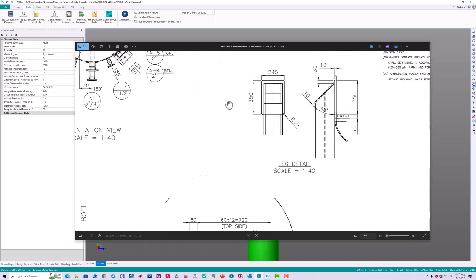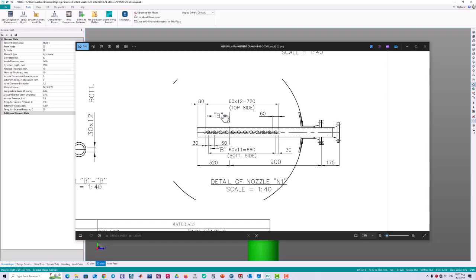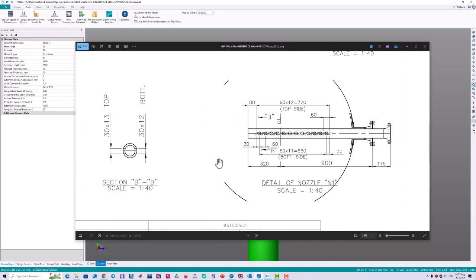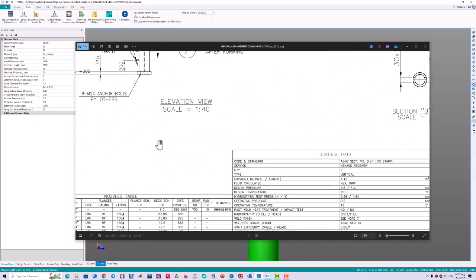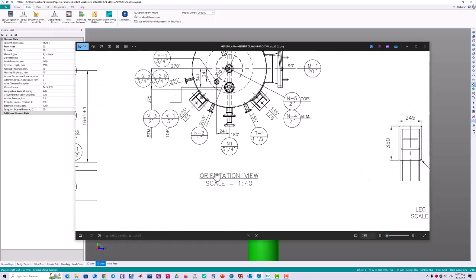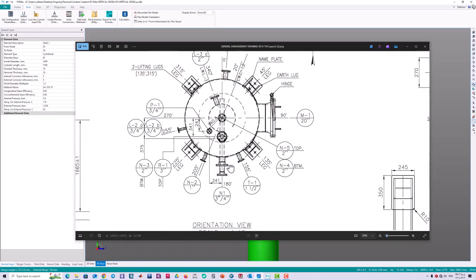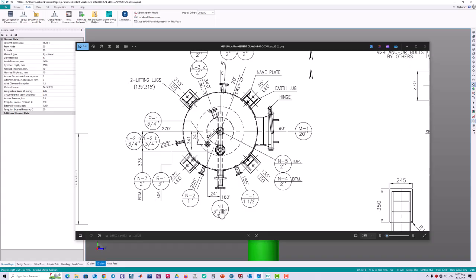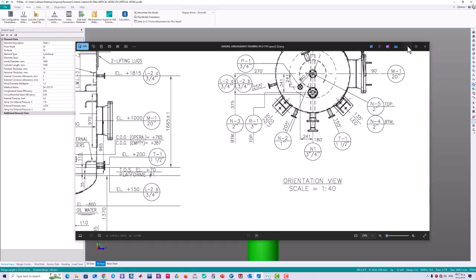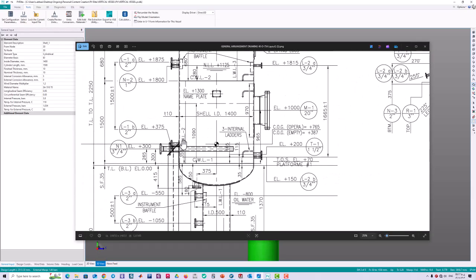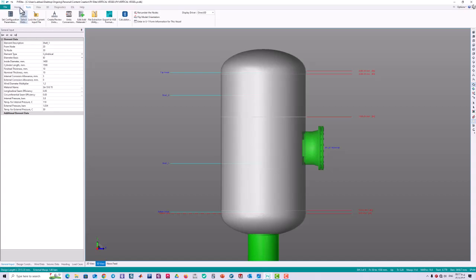This calculation is not explicitly possible in PVLite, and if we are going to calculate the 3 inches nozzle, we have to create a submodel for it. In this tutorial, we model only the N1 nozzle with 4 inches diameter.